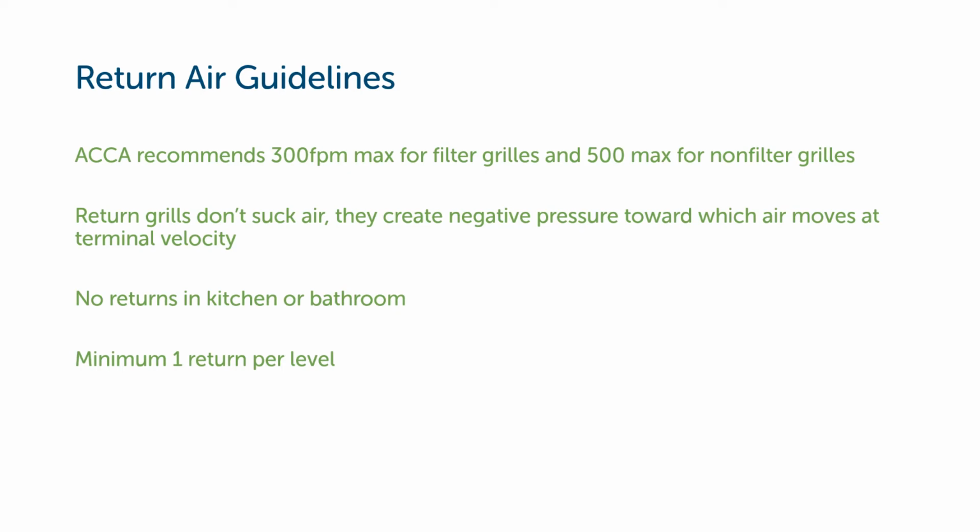Return grills work because they create a negative pressure, and the air in the room moves towards that negative pressure at terminal velocity or less. So the return grills are not like sucking air. It's not a good way to move air somewhere.